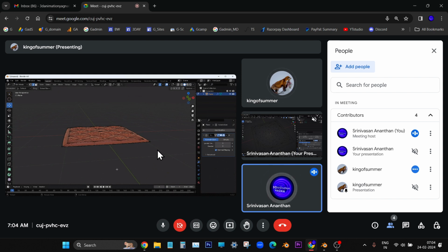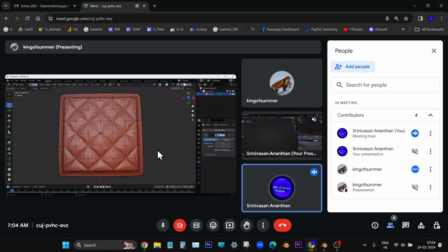Now we have to add a cloth effect for this. Before that we have to do the UV unwrapping. We'll make the UV unwrapping simple this time. Go to top. The boundary edges we added and made double using the bevel, right? We made it beveled and then duplicated it. So any one boundary edge loop we have to select and mark seam.